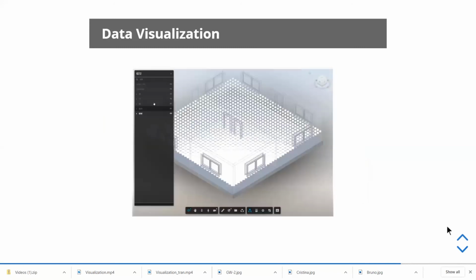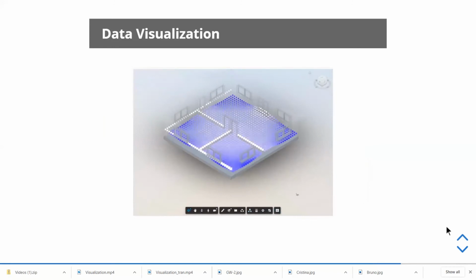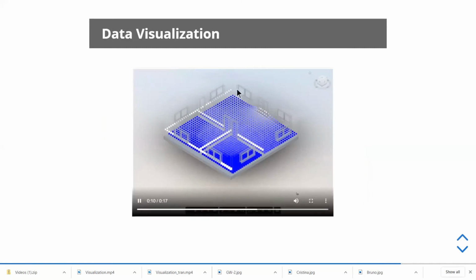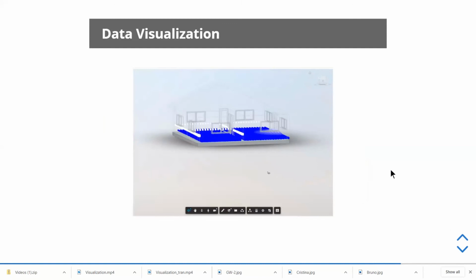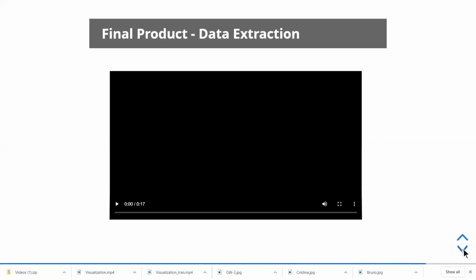This is for the small house, which we did. We were successfully able to tie the information back in. You can see how, when the data reads, these are all walls, and we had to eliminate those details when we inputted the data. We also had issues initially: if the project base point is not defined properly, or the location is not set properly, then the alignment would not happen properly. So those things we had to manipulate. But this is our final product.